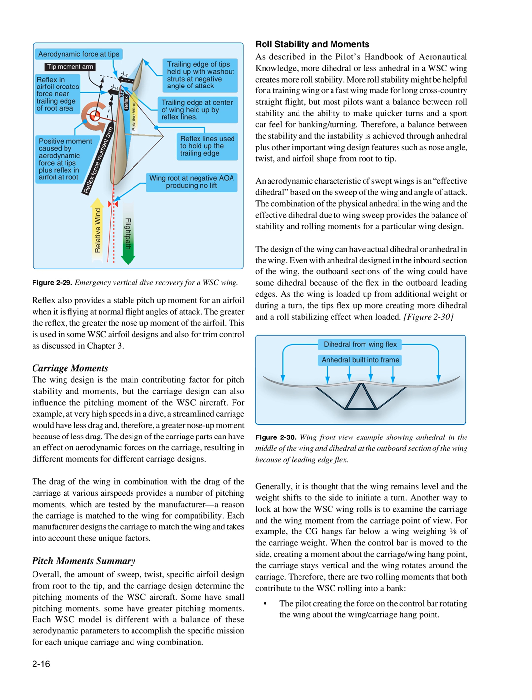Some have small pitching moments, some have greater pitching moments. Each WSC model is different with a balance of these aerodynamic parameters to accomplish the specific mission for each unique carriage and wing combination. Roll stability and moments, as described in the Pilot's Handbook of Aeronautical Knowledge. More dihedral or less anhedral in a WSC wing creates more roll stability.